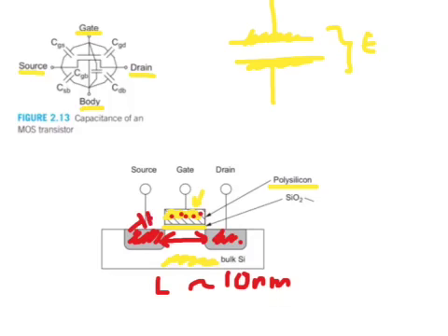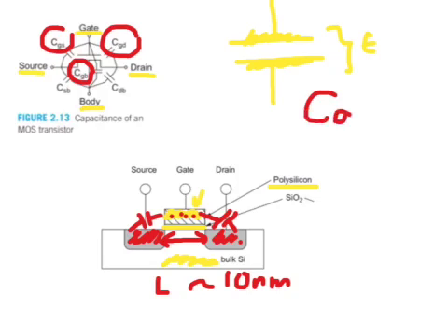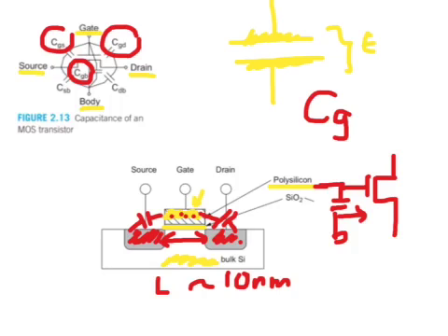So there are capacitances here also contributing, and together the gate to source, the gate to bulk, and the gate to drain capacitance form what is known as the gate capacitance. This is the capacitance seen at the input terminal of the MOSFET. It acts as the input capacitive load of the MOSFET, as well as the output load of preceding logic stages.